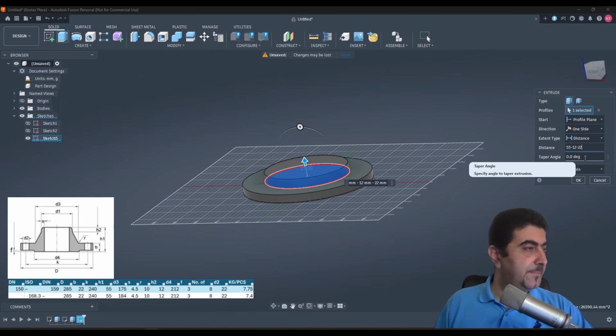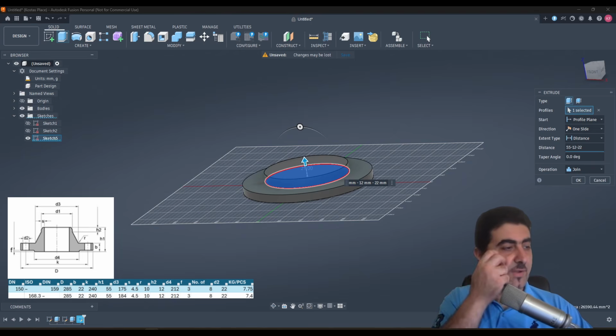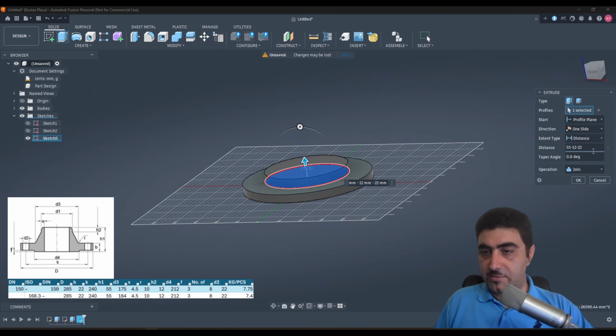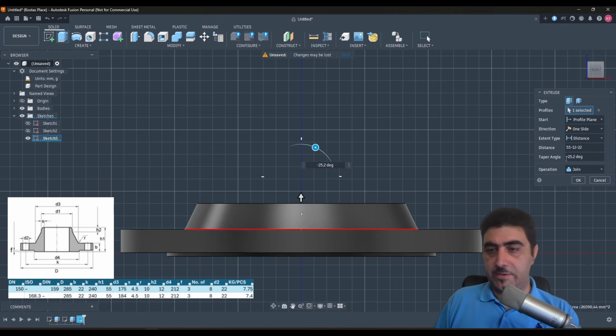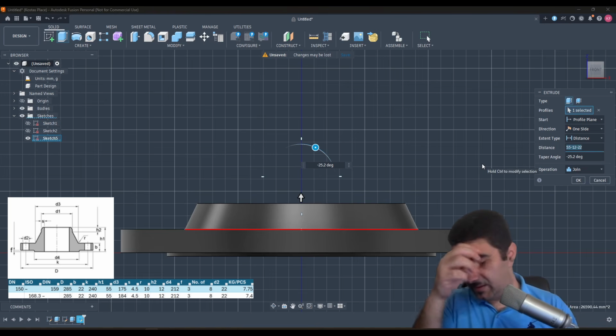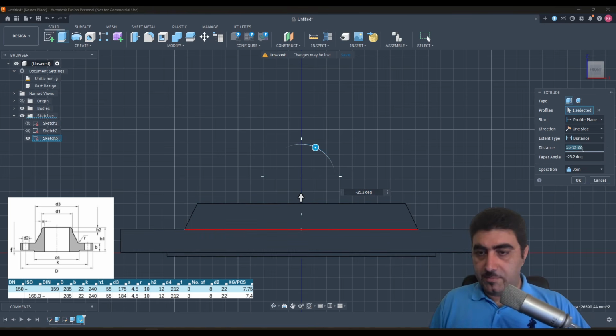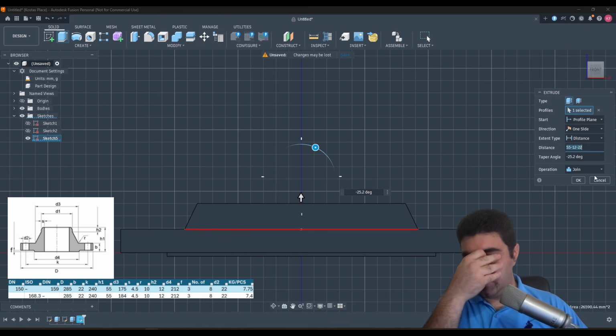And that needs to end up at a value of 168.3. So the taper, what is that? 4.8 degrees? Okay, so I could either loft it or I could do this with math. Doing it with math would mean I go from 184 to 168.3, so go inwards.